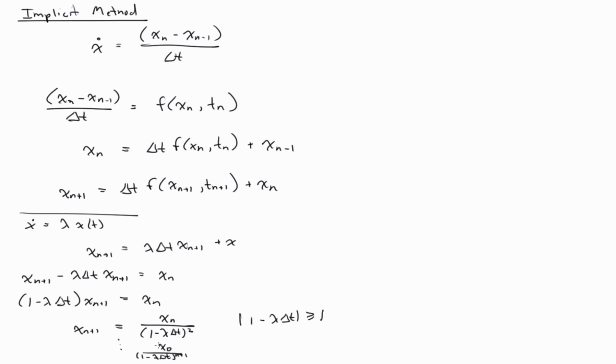Okay. So we don't really have a great general theory for nonlinear problems. So a lot of times, what we do is we use the theory from, specifically in the explicit case, the same thing. We have that critical time step calculation, but it's only valid for linear problems.